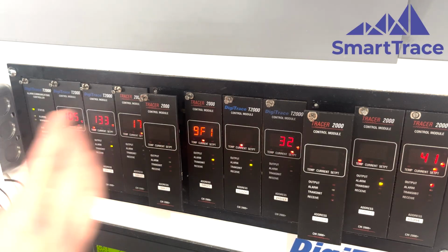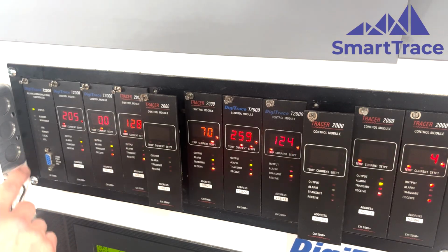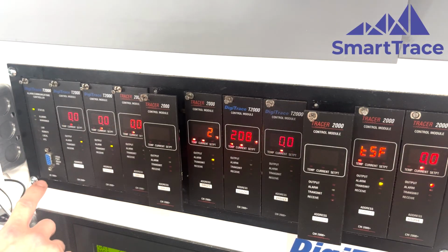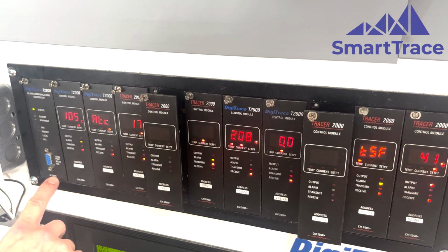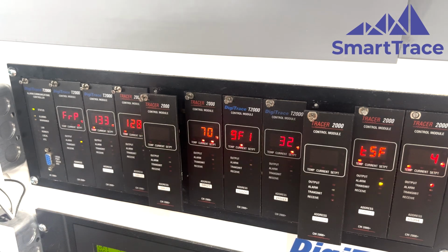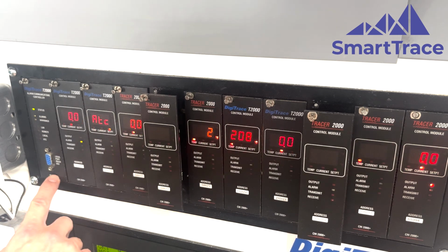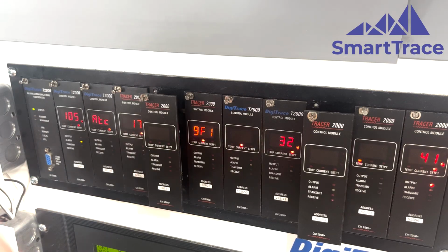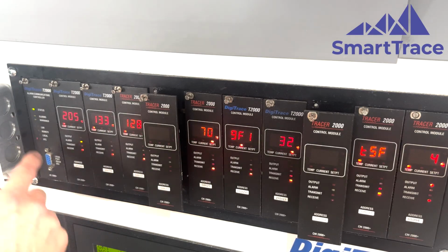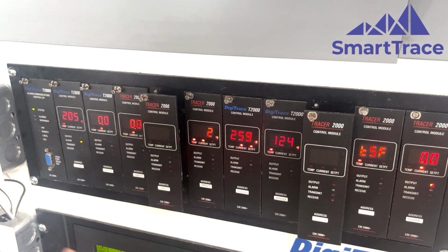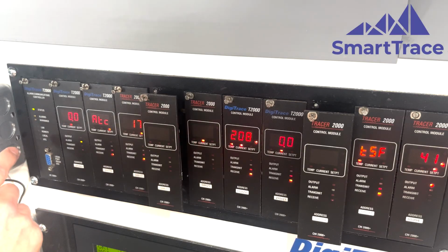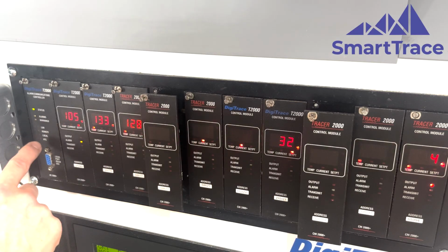So specifically, when you come up to one of these heat trace controllers, typically the first controller in the first rack of a T2000 panel will be a communication card, and typically it'll be an AC2000 plus card. There are some older communication cards that were available with the T2000, but this is going to be the most common. When you come up to a heat trace controller, you need to know how you can communicate to it. The AC2000 is the communication port in which we do so.